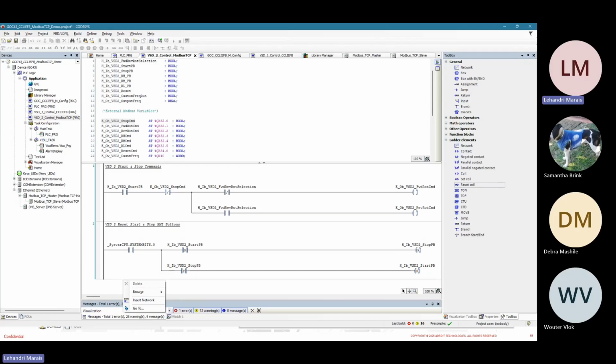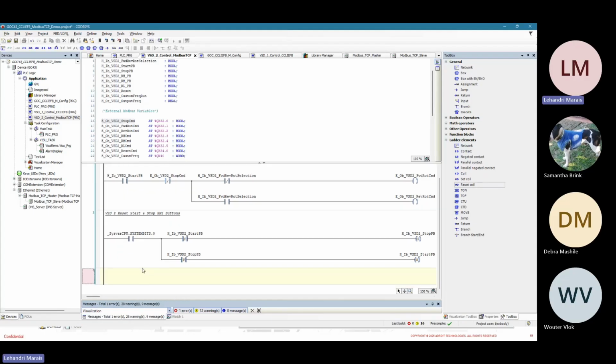Whereas for your Modbus TCP, you already have a bit dedicated to a stop command. So it's not the absence of the true states of those two bits that is required for the VSD to stop. So activating this bit will stop the VSD regardless of the state of your forward rotation command or your reverse rotation command.